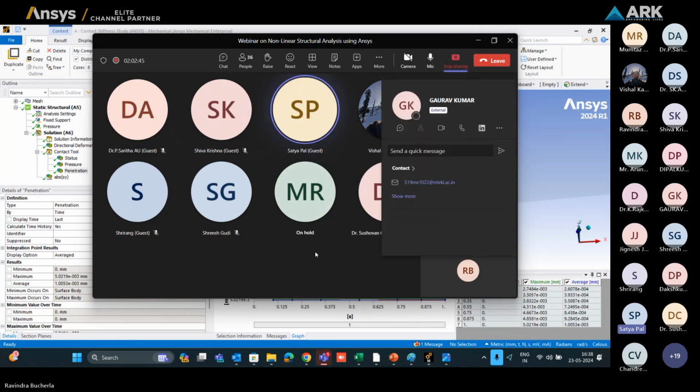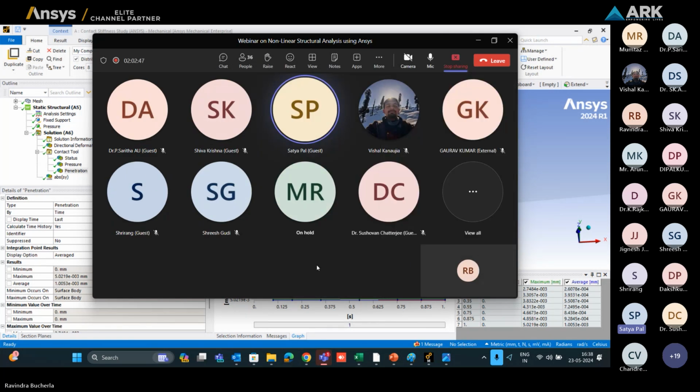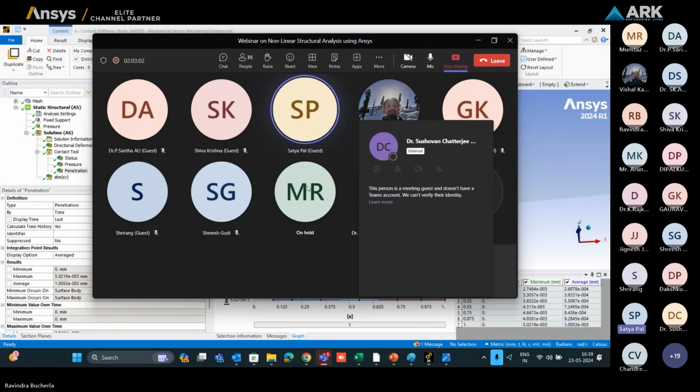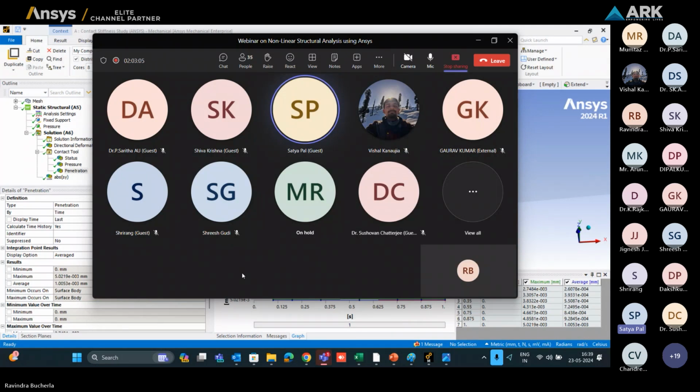I am doing a displacement control simulation of indentation of soft materials. From here, I will get the output data of load versus displacement, because we didn't apply any load. So we have to find it through reaction force, or some other force.